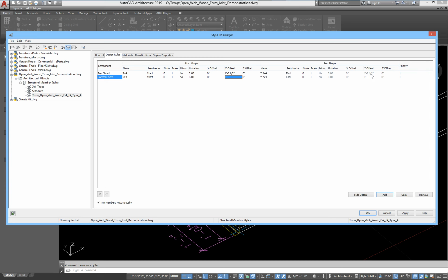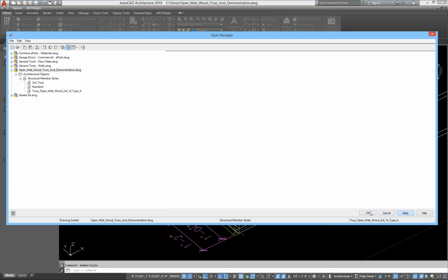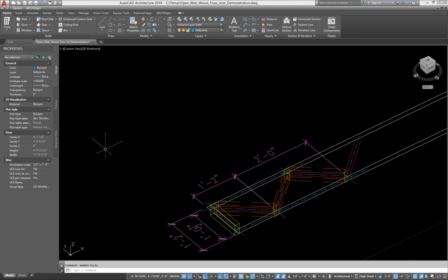and the end 1.5 inches above the other through the center line of both, because those profiles, if we go back here, let's see, 2x4, it's that profile. If you were to look it up, see how it says section, it was brought in automatically. The profile was designed from the center point, so that's why I'm talking about the center point of these. I'm not going to do any more to confuse you. I would stop here, apply, OK, and actually draw what you've created to verify that it's working.